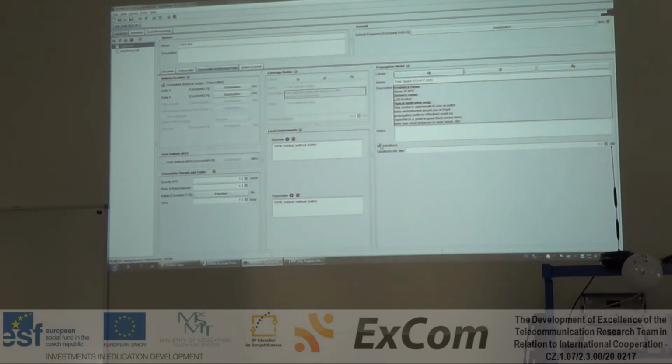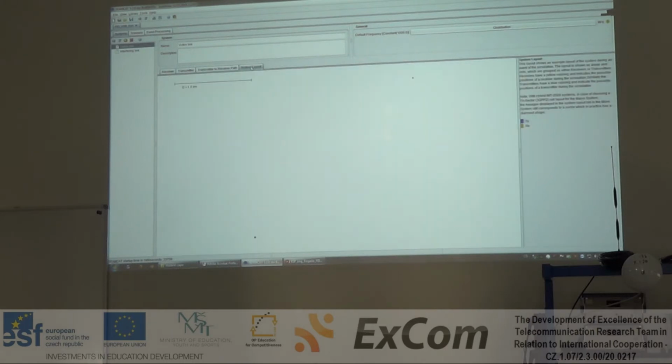Finally, here we have a button called variations, and it is used to include noise on the signal with a 1 dB standard deviation. We have to do that here because the systems will not move between them. So if they are not moving and we are not inserting noise, the signal will always be the same. In that case, I will insert some variation on the signal, which is mostly thermal noise on the systems.